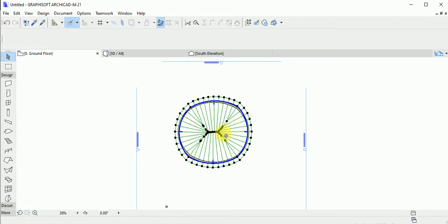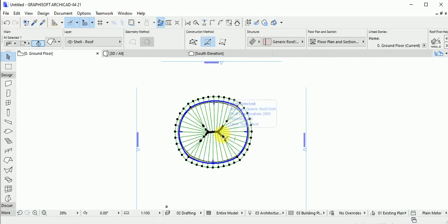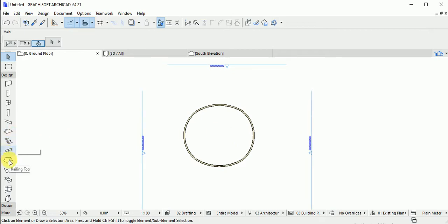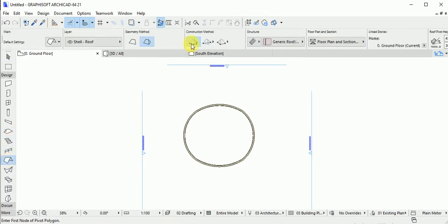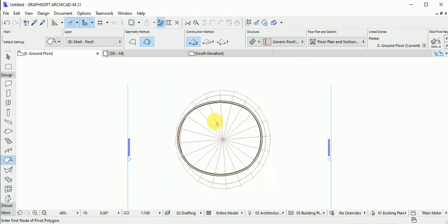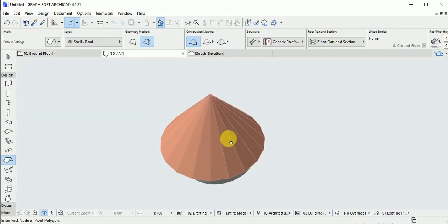But still, you can delete this particular roof. Let me assume I deleted this roof. You can still go to your roof, click on this particular method, then you highlight, touching the side of the wall. You can still draw it according to that particular method to follow the shape of the wall. Based on that, you have touched it to go in circular form. So you see, this is a circular form method. So this is another method.